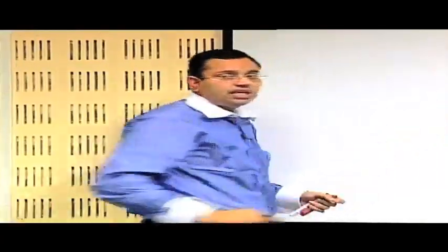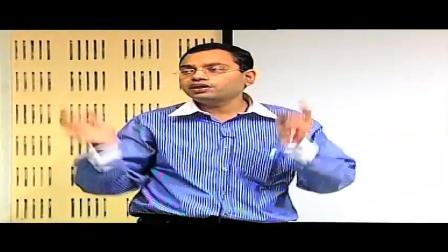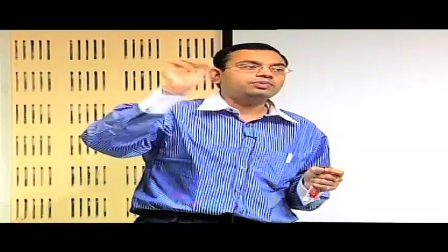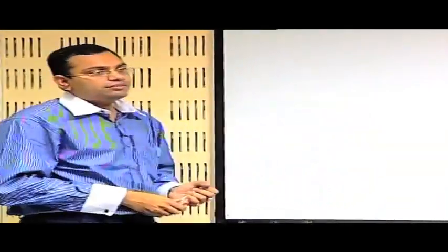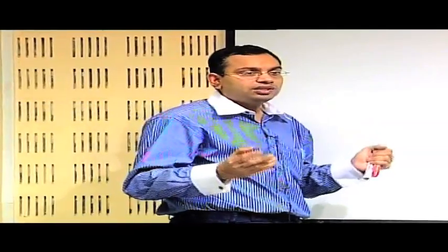Of course, if you have a very high Reynolds number flow and a bluff body, or a body of such a shape that flow separation occurs quite quickly, then the form drag or pressure drag remains the more important concern than the skin friction drag, and then the drag coefficient may become independent of Reynolds number at a very high Reynolds number. Now if you have a flow where viscous effects are important, you represent that with a drag coefficient, which is a combination of the skin friction drag and the form drag or pressure drag.